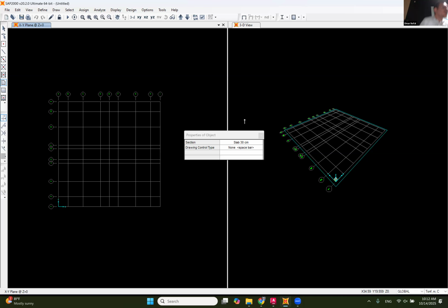And here, when I open this, it's asking me what cross section you want to use when you draw the slab, 30 centimeter or something else, because you can choose between multiple things. If you look here, you will find the wall, but right now I'm drawing a slab. So if you pick the one that has the poly area, you have to draw the slab point by point. Can you see? Like this and this. And once I'm done, I can escape.